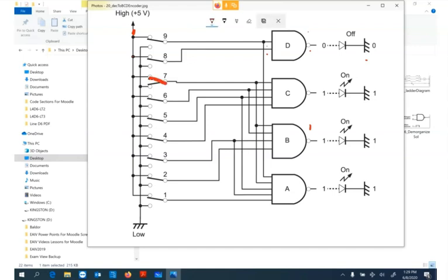Let's say that 7 is here. Thinking of this as your least significant digit, this being 1, 2, 4, 8, you'd expect when you push button 9 down here that this would come. We need a 0 there. We need to turn this output to a 0. We need a 1 on, I should say, to turn that on. And a 1 down there. That would give us a count of 9.